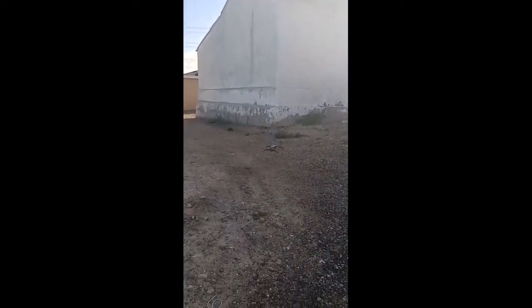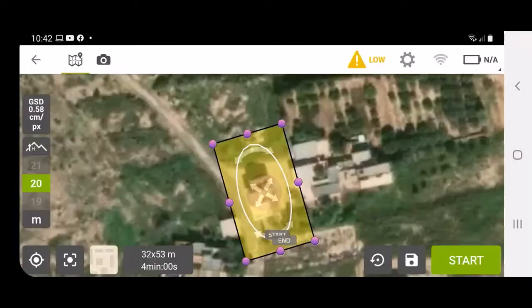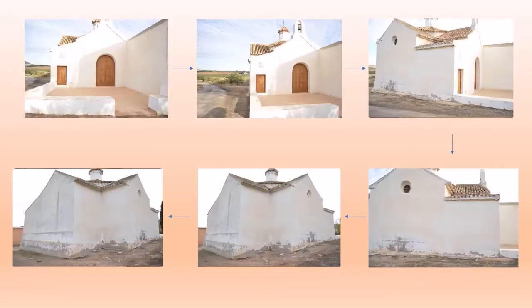The camera icons depicted on the grid indicate each of the photographs the drone has taken. Upon completion of the flight mission, the drone will proceed to its mission end point and will automatically land in the same manner as it lifted off. Subsequently, we made a circular flight at a lower altitude to obtain photographic information of the elevations. We completed the aerial photogrammetric session with a selection of ground support photographs with the intention of completing and enhancing information not fully visible from the air.